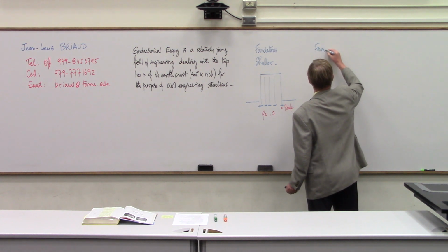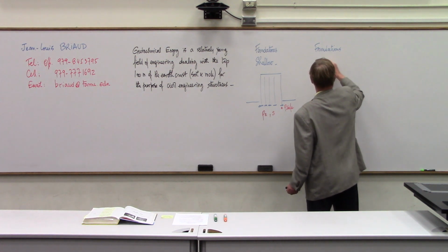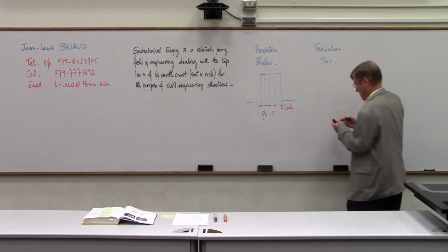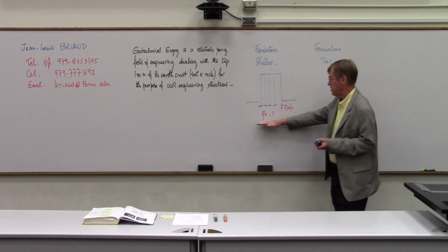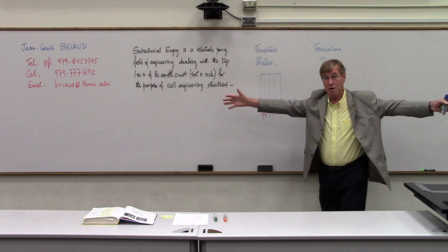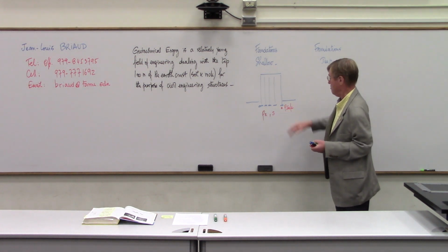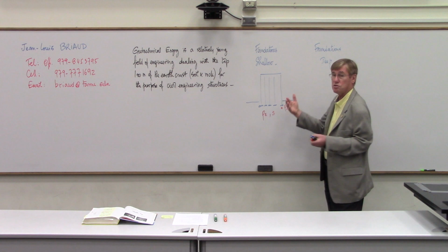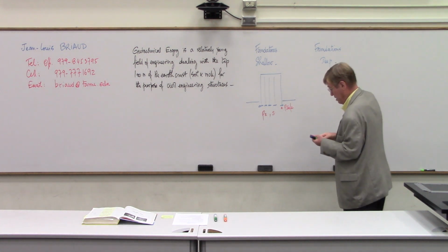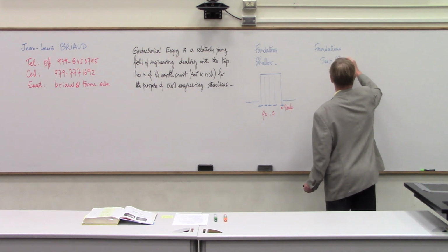The other type of foundations that we deal with is deep foundations. If, for example, we calculate q ultimate and it's very small, and so the footing has to be very large because the building weight divided by the area has to satisfy the bearing pressure, or if the settlement is quite large, then shallow foundations do not work, and we may have to use piles. So deep foundations, we call them piles.